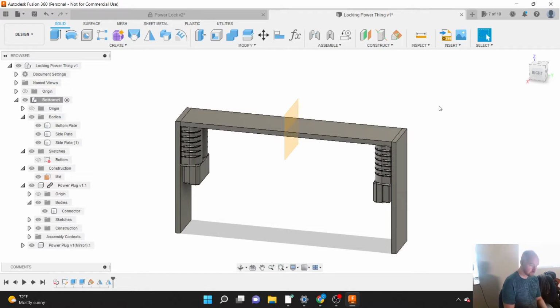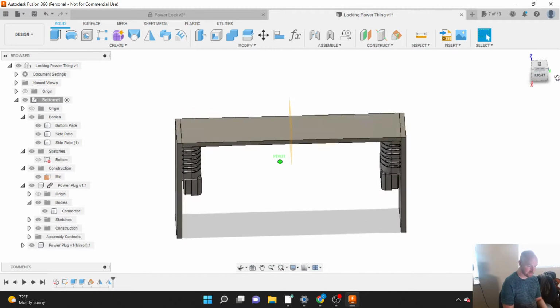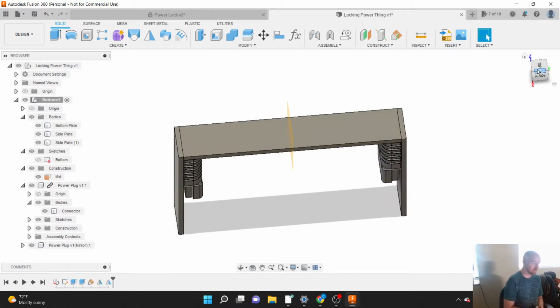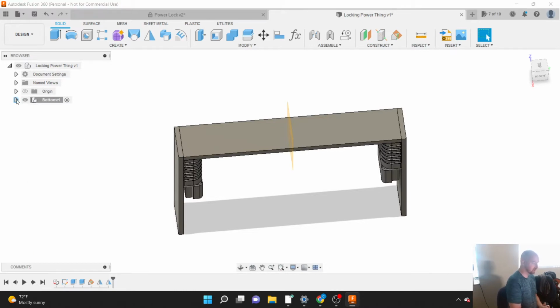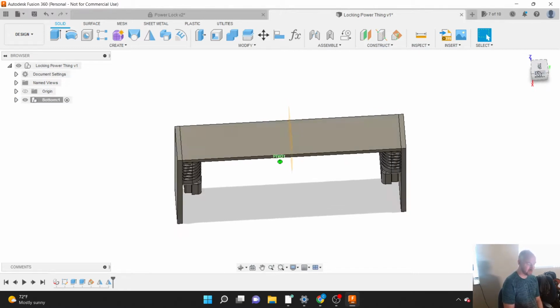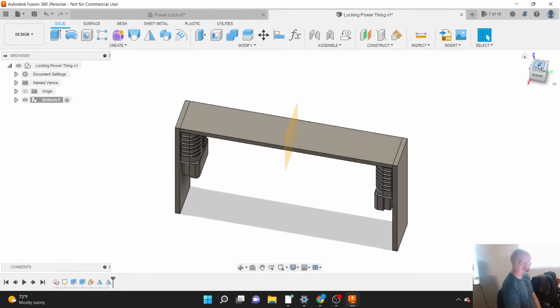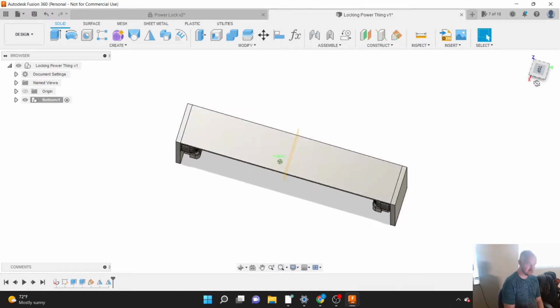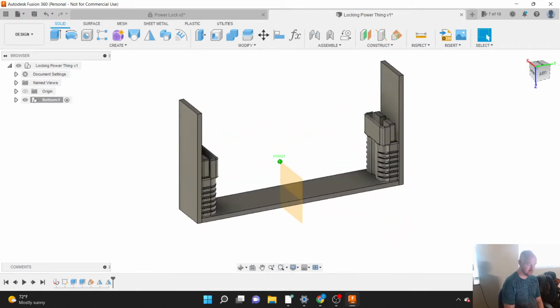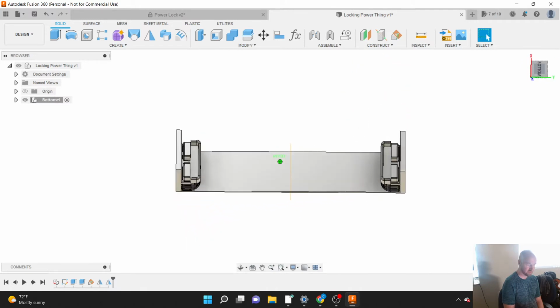I'm going to do one last thing, and that is we drew this. I said, hey, it makes more sense to draw the bottom first, but right now our thing is upside down. Just as a point of order here, my navigation cube tells me that this is the top, and you can actually tell your navigation cube what side you want to be the top.